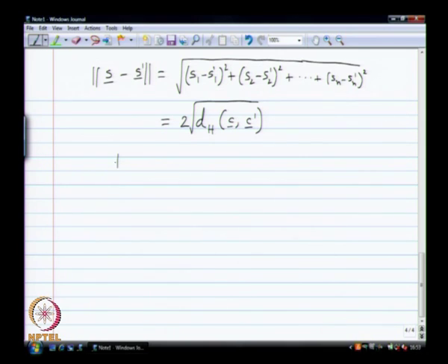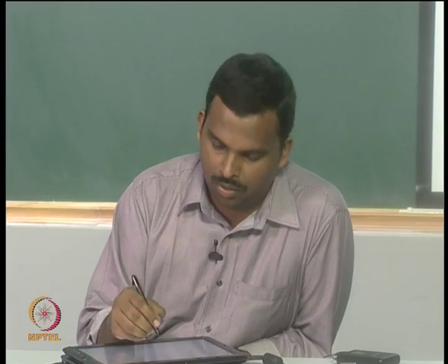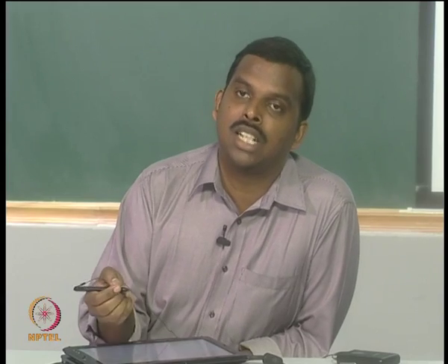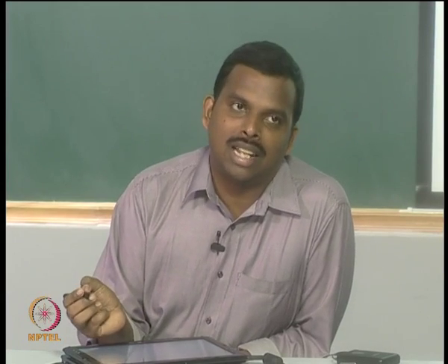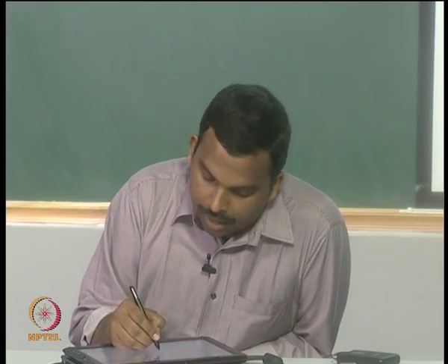So essentially the pairwise error probability between C and C prime simply becomes, remember this is BPSK AWGN with minus 1 plus 1. If that minus 1 plus 1 is not there, there will be some nasty constants floating around. That does not change the final answer though; once I express it in terms of Eb over N naught, the final answer becomes exactly the same. Okay, so that is the idea.